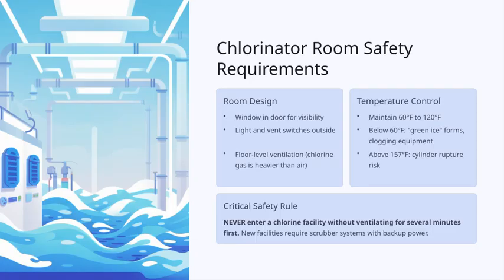Let's take a closer look at the safety requirements for the chlorinator room. First, the room should be designed with safety in mind, including a window in the door so you can see inside without entering. This helps you assess the situation before stepping in. Additionally, switches for lighting and ventilation should be placed outside the room, making it easier and safer to control these systems without unnecessary entry. Ventilation is especially important here because chlorine gas is heavier than air, so the room needs floor-level ventilation to effectively remove any fumes and prevent dangerous buildup.